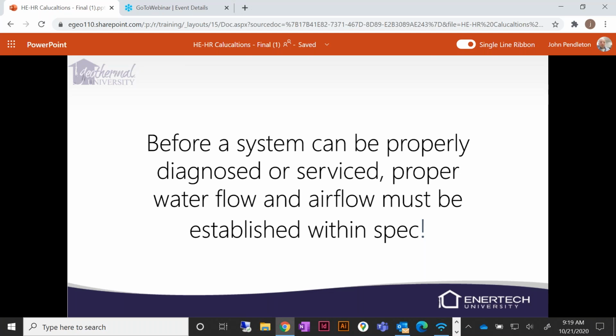Let's say you should be running 1740 CFM; it won't flash 17.5 flashes. It'll flash 17, then give you a weird blink, letting you know it's getting ready to start over. But it'll get you in the ballpark of what your CFM should be. So you can count your CFM blinks and see what you're moving.